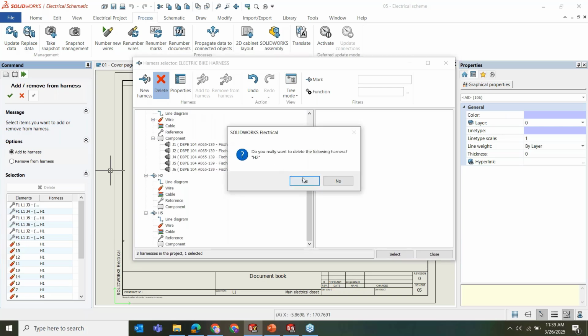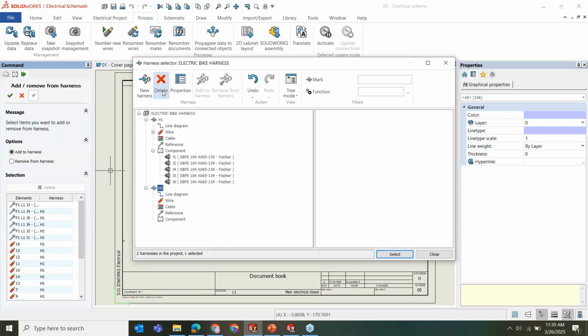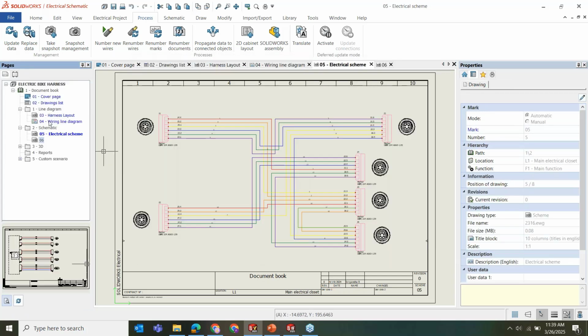So you can see here, I'm just going to keep it clean and stick to the first harness only. I've just added this to a harness. Now grouping has been done. Whenever I select harness 1, J1 to J6, all of them are selected. But I have not linked J4 yet. So only the wiring between J1, J2, J3, J5, J6 is what we are going to see now.